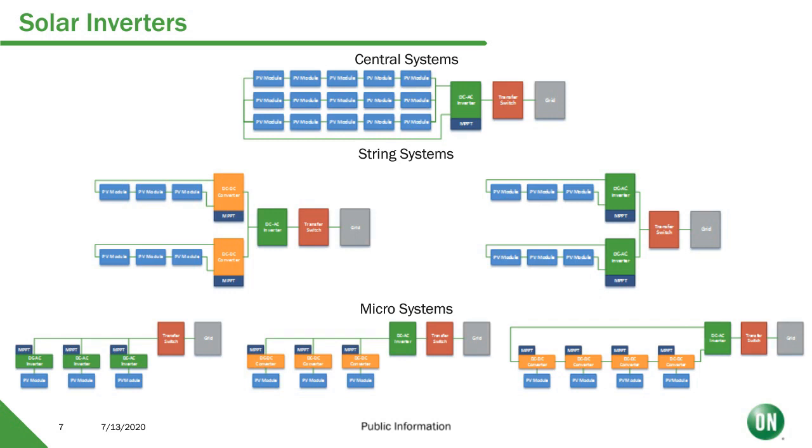These can be microinverters or DC to DC optimizers that will feed into a string inverter. These ultimately give the best efficiency because they can control the output power at a panel level compared to a string or a central perspective. So highest efficiency can be generated from a microinverter, but you do have a more costly solution here as it involves more components.